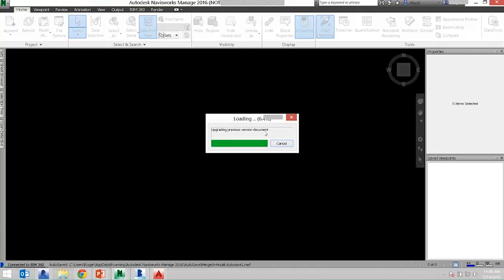It's worth mentioning also that if you bring a Revit file directly into Navisworks and you create a view called Navisworks inside of Revit, that's the view it will use to translate all the information into the NWC file. Fantastic.